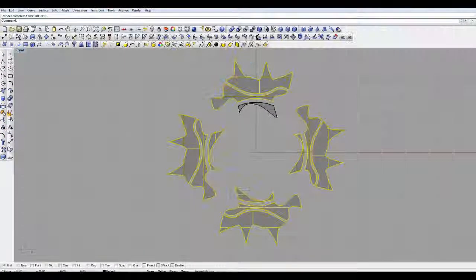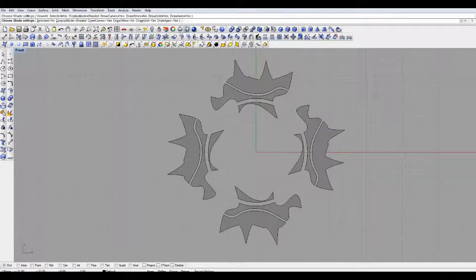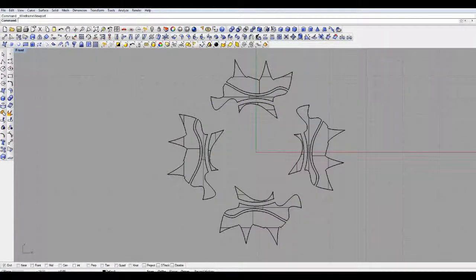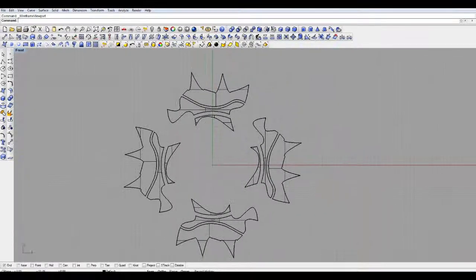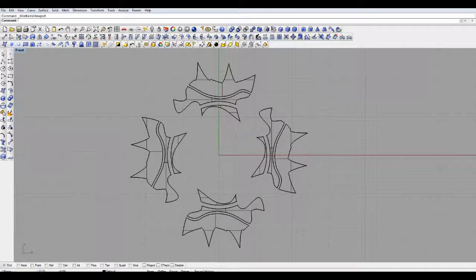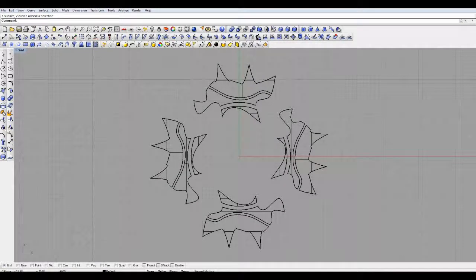So, using the different surface commands and property settings, you can basically assign all sorts of different colors or properties based on how you want your design to look. So I think that will do it for this particular lesson. The whole point of this was to go through some of the more advanced commands, primarily the trim command, since that's one of the more important things you'll need to learn how to do.